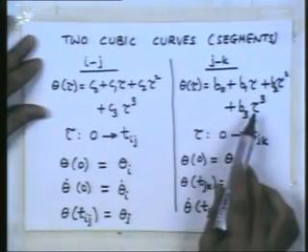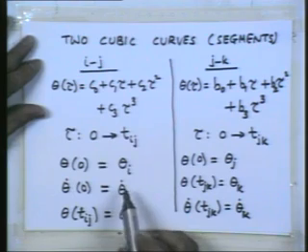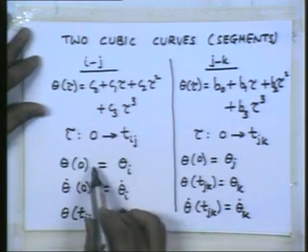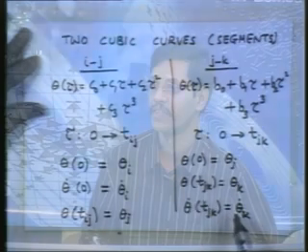Among the 8 coefficients to be determined, we need to get 8 conditions or equations to be solved for those 8 unknown coefficients, and what we are writing down here is only 6. We need to generate 2 more, and those 2 more equations are generated based on the fact that at position j, velocity has not been prescribed any value. We want a smooth motion. So I would say that the velocity and acceleration at the position j be continuous. These 2 conditions I will use to generate the necessary 2 equations at the position j.